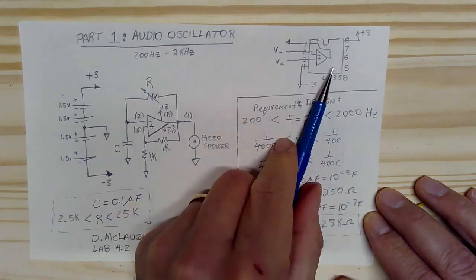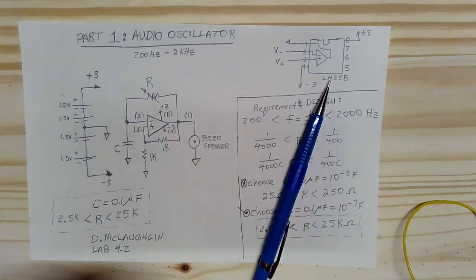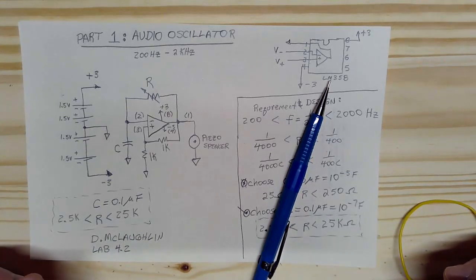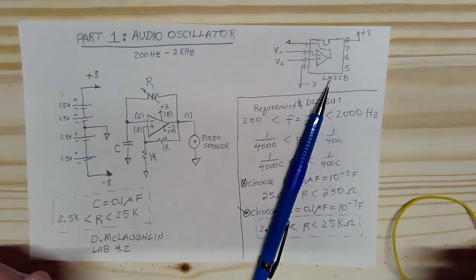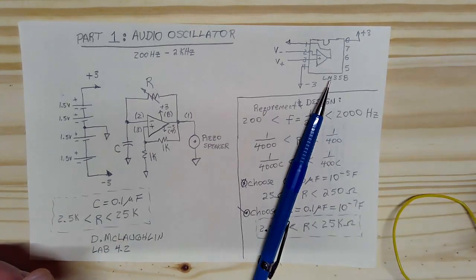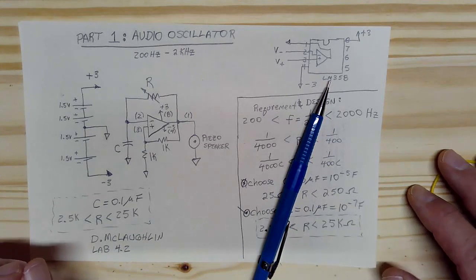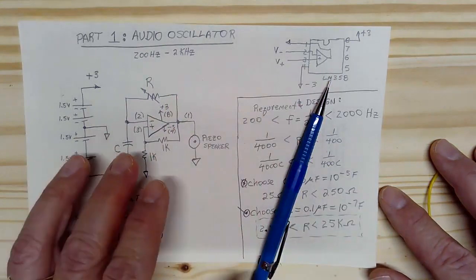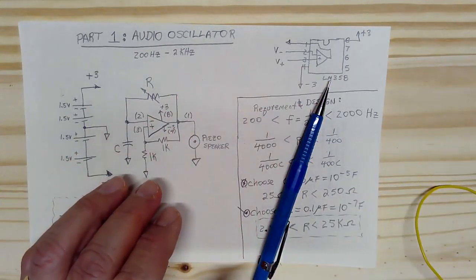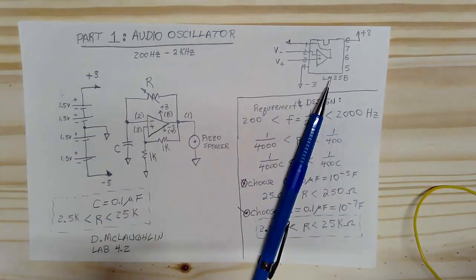Now, the op-amps that we have in our kits, the LM358, actually have 2 op amps inside each chip. So if you want to, you could build this entire lab on one op amp chip. But if you do that, the circuit gets pretty dense and it's hard to actually make the kinds of adjustments that I'm going to show you how to make when we tune up the frequency. So the way I'm going to build this is I'm going to build the audio oscillator with one chip on one circuit board, and then I'll build the blinking LED with a separate chip on a separate breadboard. That way we're keeping things as clean and neat as we can.